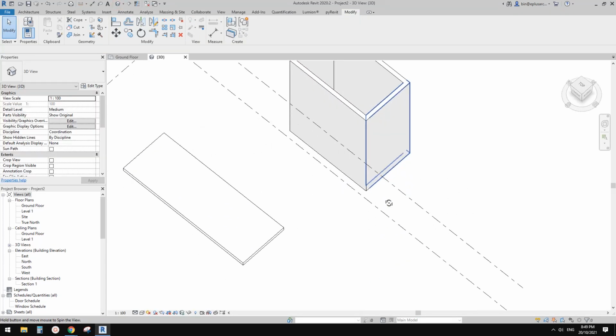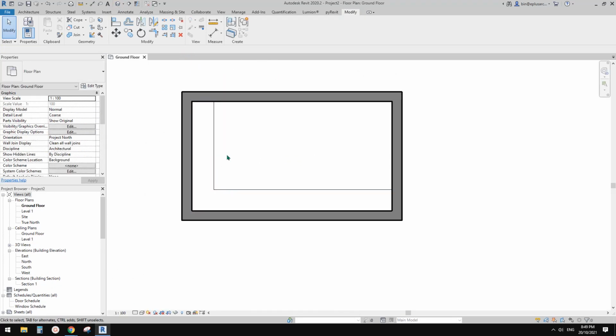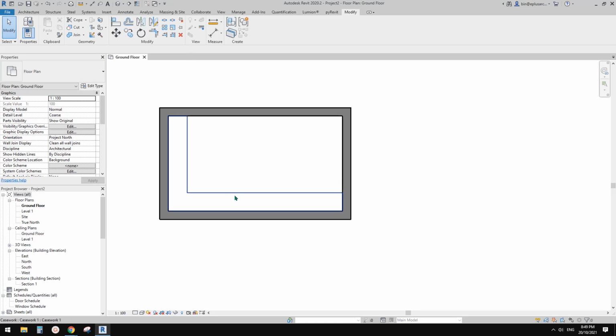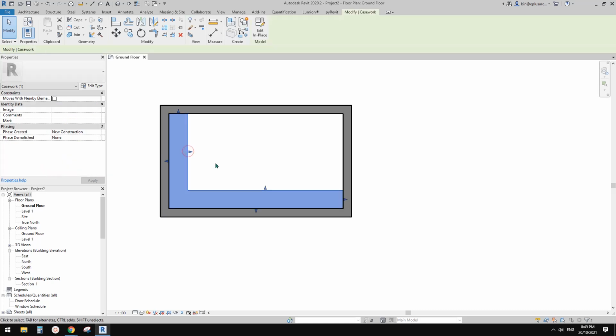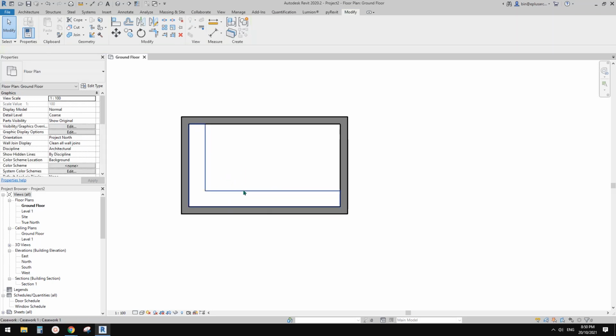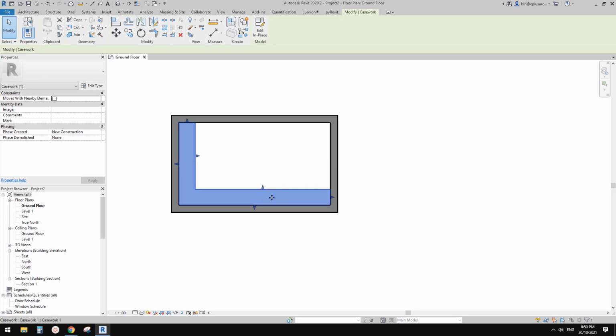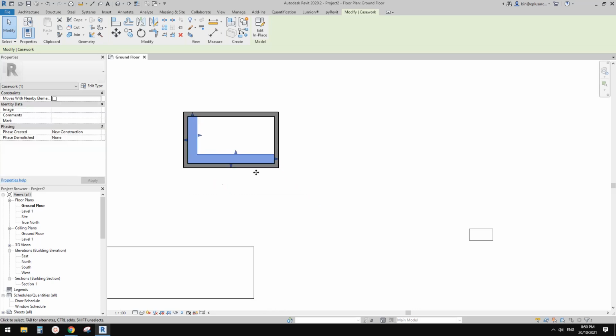If I go to 3D view, you will see something like this. So this is useful when, for example, the dimension of the project of these walls will be different to other projects. So sometimes you just need to quickly model a model in place as some joinery, and you probably won't use this in other project. So it's easier to do it this way. So model in place, and don't worry about this.